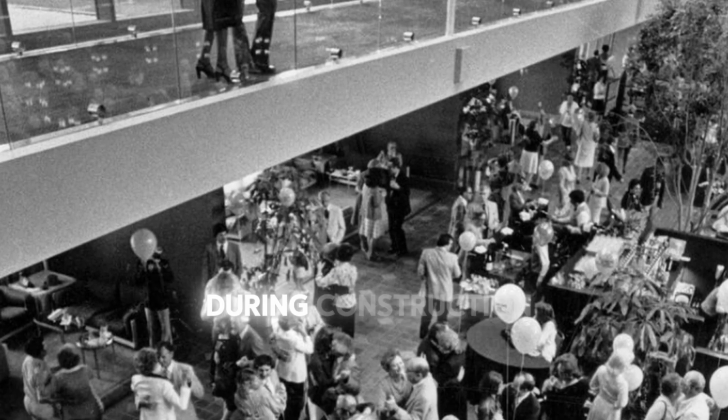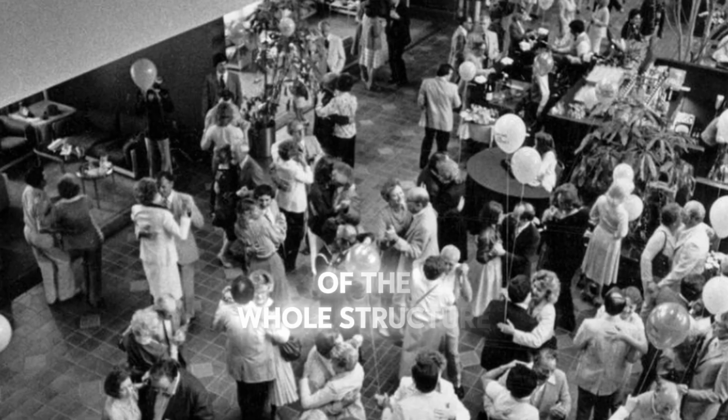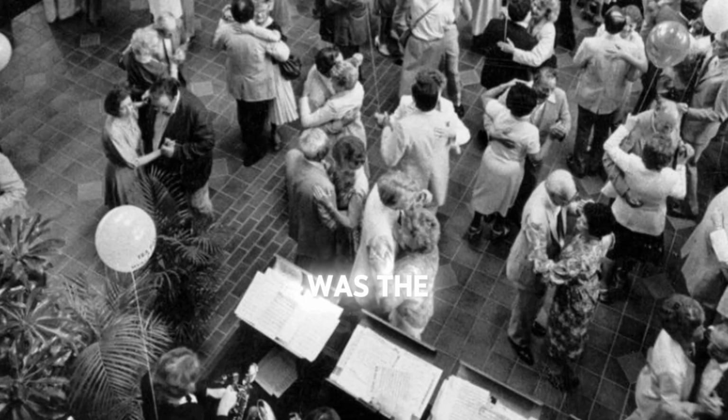During construction, a section of the atrium roof had collapsed, which should have prompted deeper scrutiny of the whole structure. And in the months before the failure, hotel staff reported the walkways moving noticeably when people walked on them. The night of the dance was the first time those walkways were heavily, statically loaded. People stood on them to watch the dancing below.